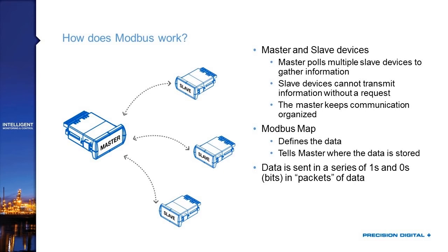It's all going to get done in the Modbus scanner, and you're going to program the scanner to say, these are the device numbers you're going to read, this is the data type of those devices, these are their addresses, this is the register number you have to pull out of it, etc. At most, with the other devices, you're going to be programming maybe a baud rate or an address so that each one has a unique address, and it's fairly simple.